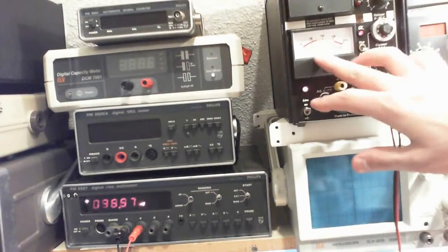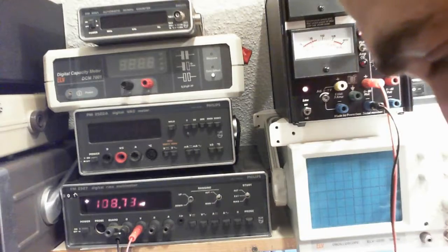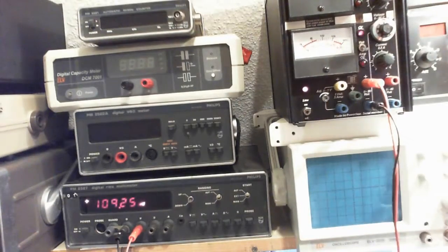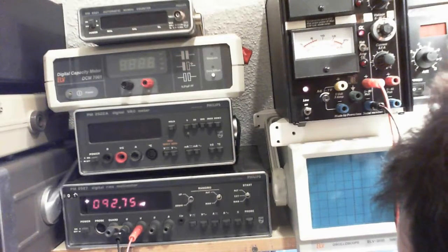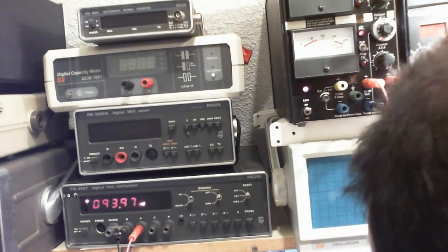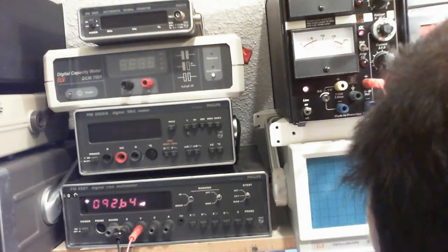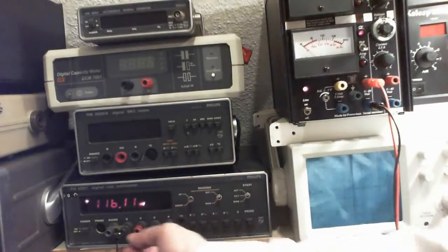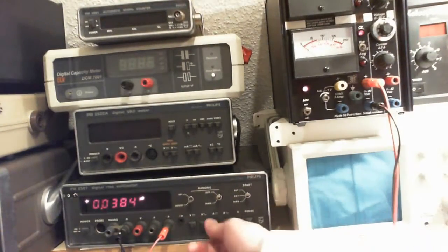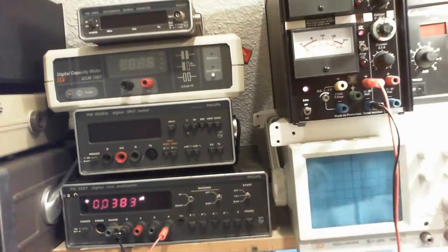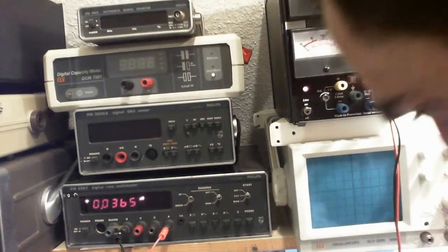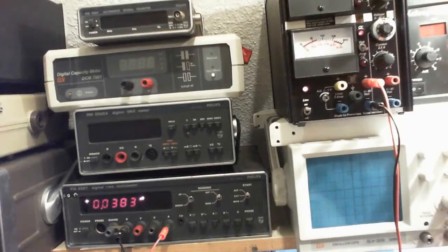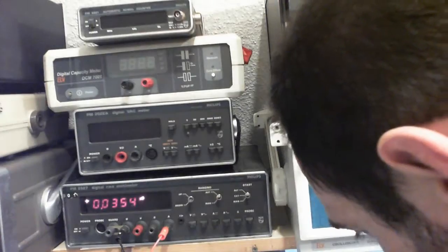Now, if you observe here, as I disconnect the lamps, this amp meter is just dropping down. See? I don't know if you can see it actually. I'm connecting it and disconnecting it, and the needle is going up and down. So now I simply set this to amps, AC, DC, and now this becomes an amp meter. I put this amp meter between the load and the power supply, and I don't know which one is positive, which one is negative. So positive goes to positive, negative goes to negative.